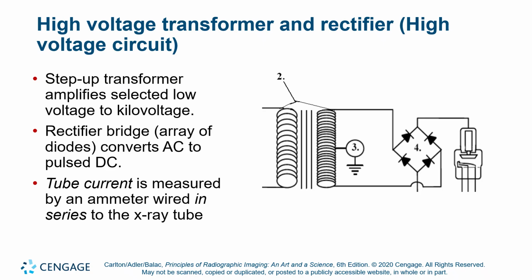And then coming off the bottom, I want positive charges. Yeah, they do have it drawn right. Good. Okay. And then finally, that's the X-ray tube in parallel. Now you can see that the X-ray tube is running parallel to the secondary coil of the transformer through the diode, but still in parallel.